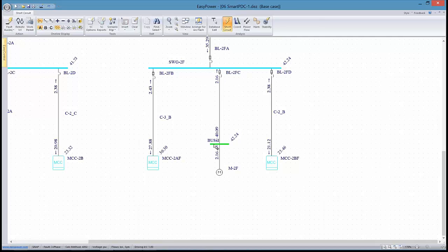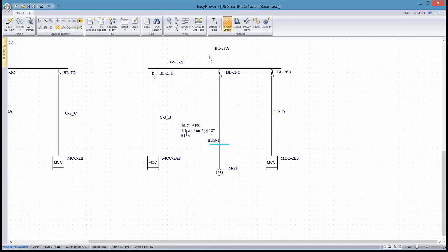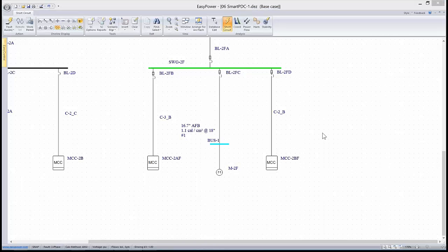And so when we produce incident energy just for that one bus alone, you can see that it may be quite a bit less if this is where we're going to be doing the work, because of the ability to include this particular breaker settings, as opposed to when we didn't have this bus in the area. Just something to consider when you're looking at constraints in arc flash calculation and mitigating energy,